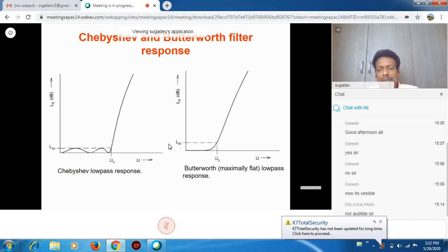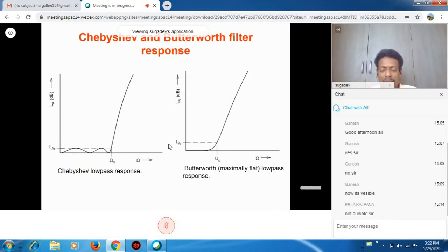That's why people nowadays use SDRs. In SDRs, we convert our received RF signals into digital, and then we implement most of the communication tasks in the software itself. For example, IF amplification, down conversion, all this people now try to use in the software domain because the digital systems can perform very well.